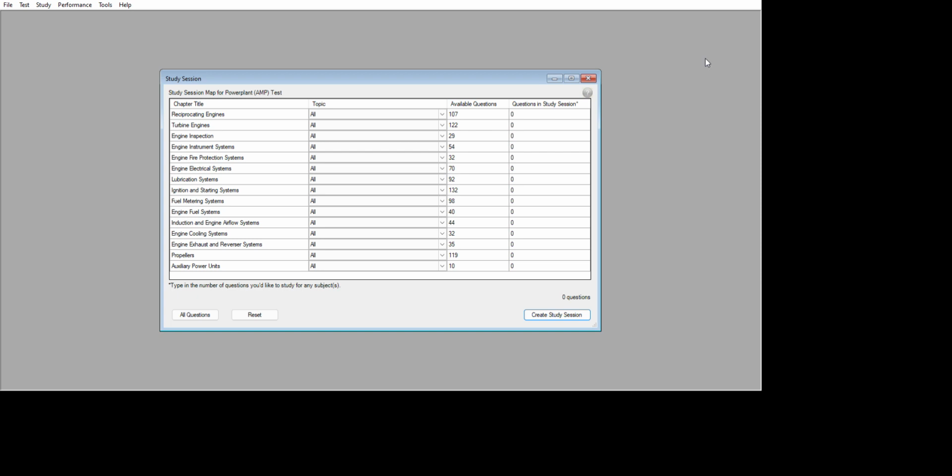When gapping a massive electrode spark plug, the wire gauge should be inserted to avoid setting the gap too close. That's false. The platinum and iridium ground electrodes used on fine wire spark plugs are extremely brittle and can be broken if they are improperly handled or adjusted. So only one is true.